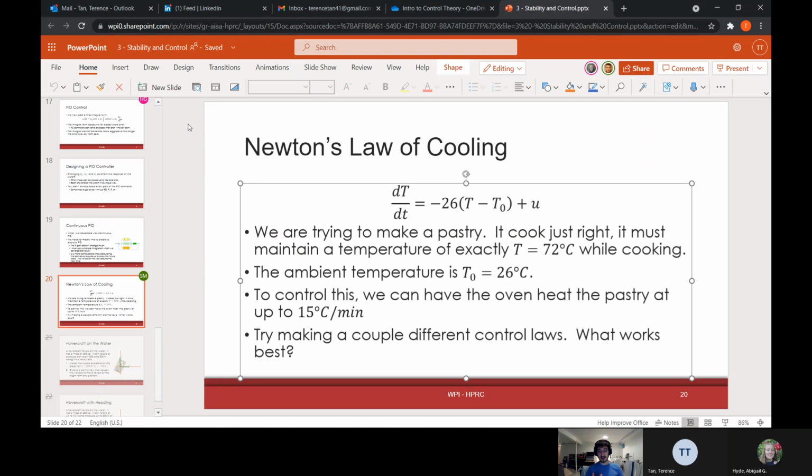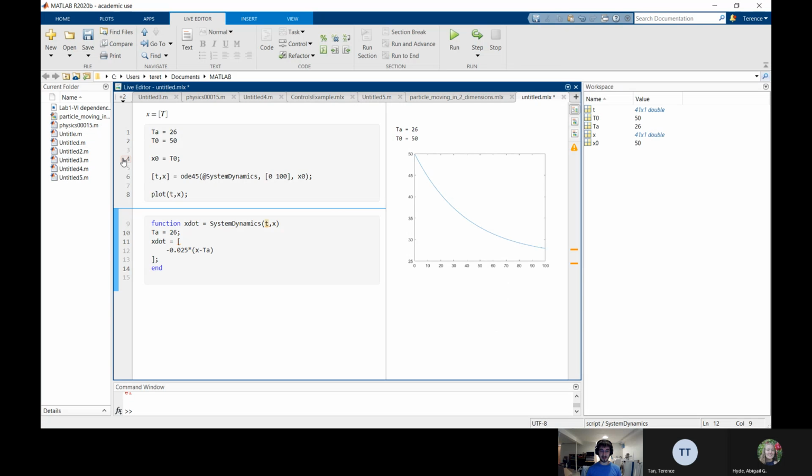So remember in the x dot, you now add a plus u there. In the function here? Yeah, that's now part of the system dynamics equation. So now within this function, we need to assign u to some value, trying to follow the control we were looking at earlier. Well, u could either be 15 or 0. So do I do an if statement within the function? Yeah, you can do that. That's allowed. It's one of the better ways to do it.